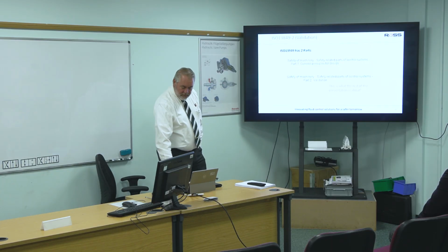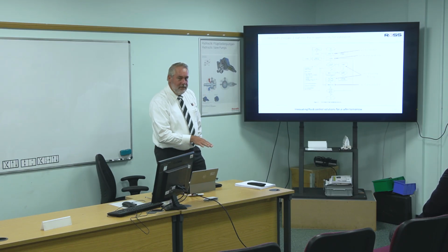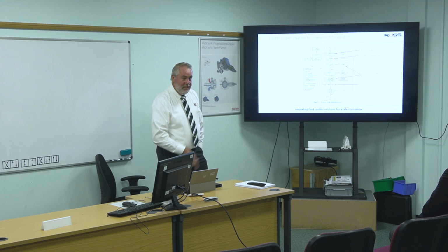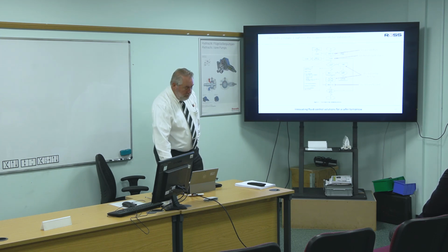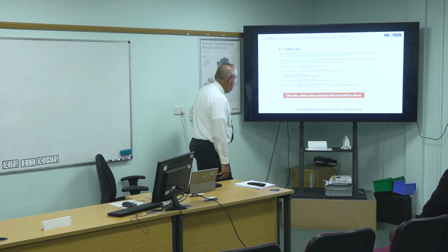After you have done your design verification, you have to validate it. And that means you have to have a documented test plan of your machine. That documented test plan will go into your technical file so you can CE mark your machine. Most people do a terrible job at doing a validation.